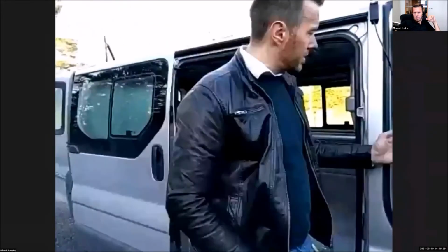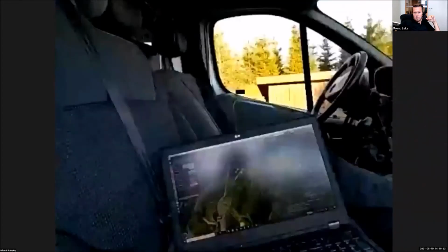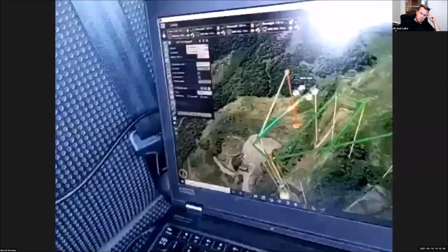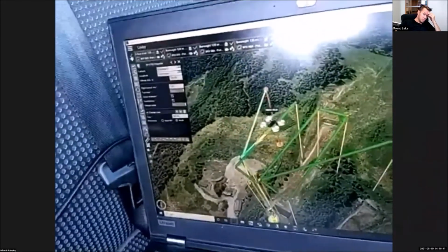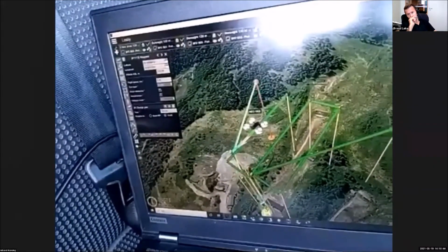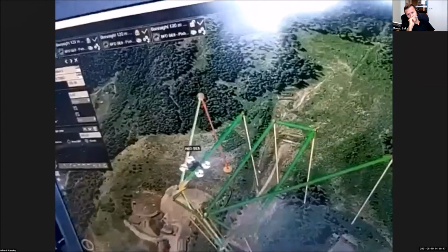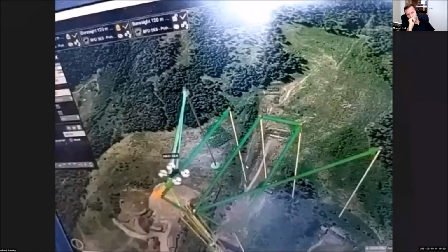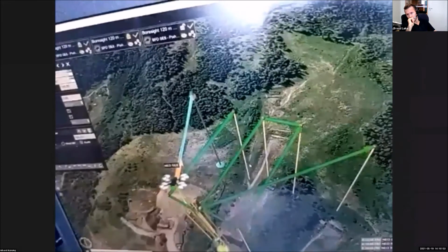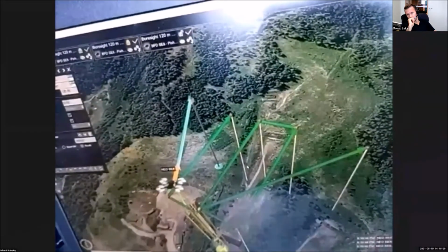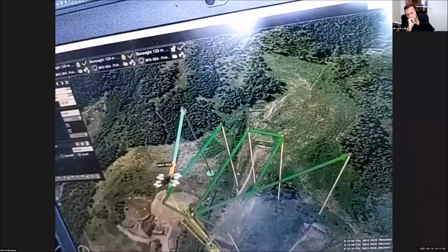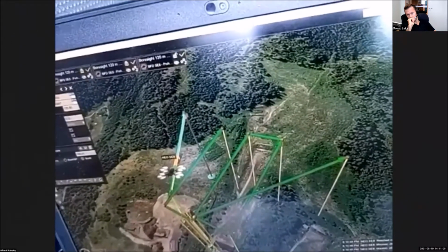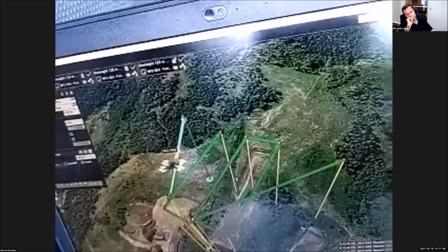Now we are basically done with the 3 flight lines, and if we go here again, it will also finish now with an alignment, also done automatically before we land. So we want to have the navigation system at the best possible performance. The Applanix APX15 inside can have an accuracy on roll and pitch of 0.025 degrees, which is about 1.2 pixels in our system. And the GPS in post-processing mode, if you use 2 IMUs, can be around 2 to 3 centimeters, while today we only use a single IMU for the payload, so it will be around 9 to 10 centimeters accuracy.